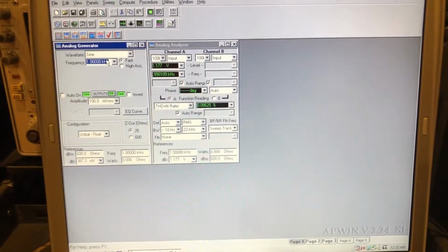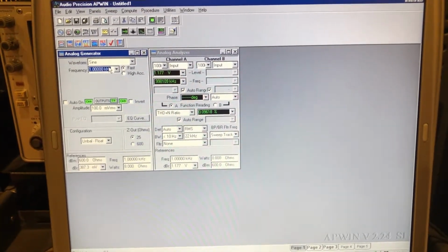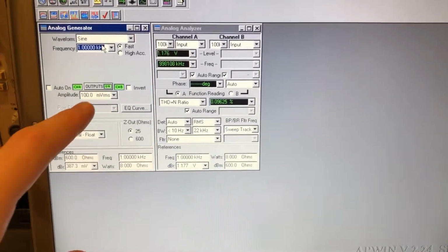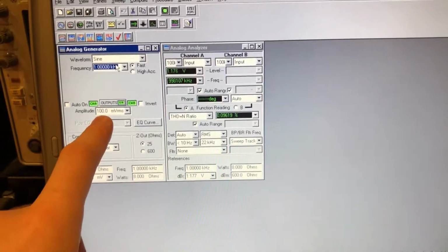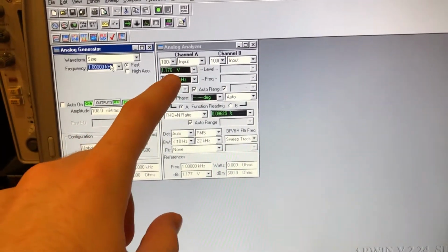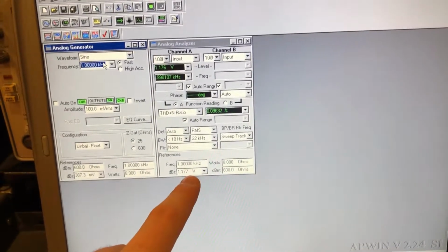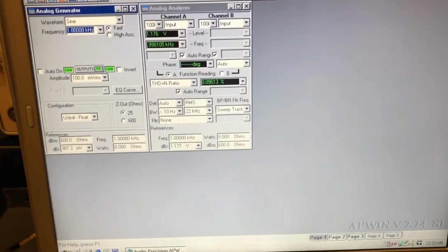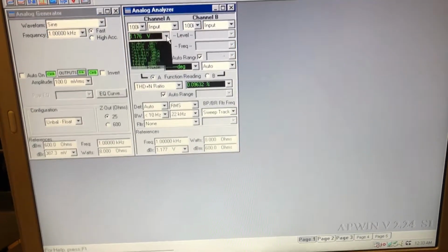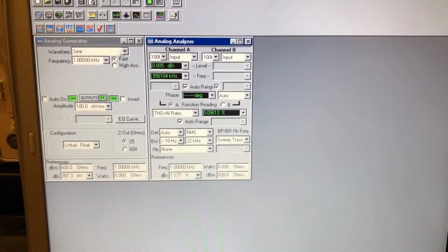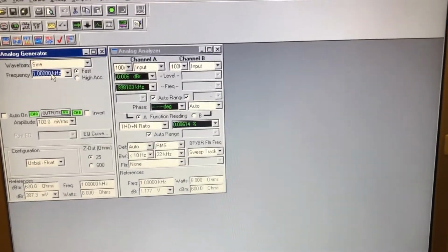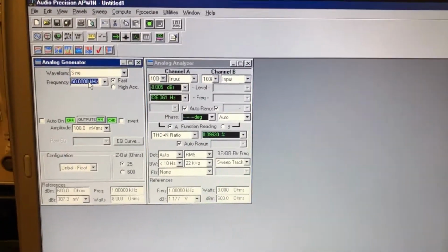The one thing we can also do is spot check the bandwidth using our digital multimeter. So back to our 0.1, or 100 millivolt input signal, here's our output signal. If I use that as a reference for what's called dBr, dB reference, and I relate my measured signal on the AP relative to that, we should get 0 dBr. So let's see what our dB roll-off is then relative to 1 kilohertz. Let's see how that changes at 50 kilohertz.